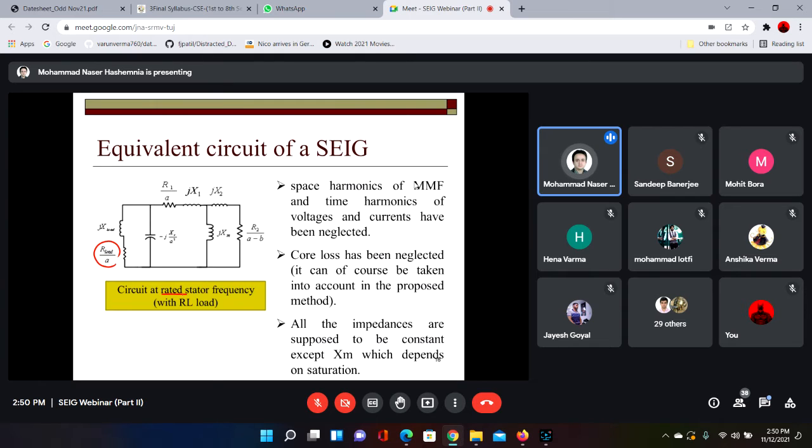At the actual state of frequency, we have constant R load, but here R load divided by A. And X, we had jA X load. In the actual circuit, X load is evaluated at constant frequency, which is base frequency. Then we divided the impedances by A, so this reactance is also divided by A, then we have jX load.